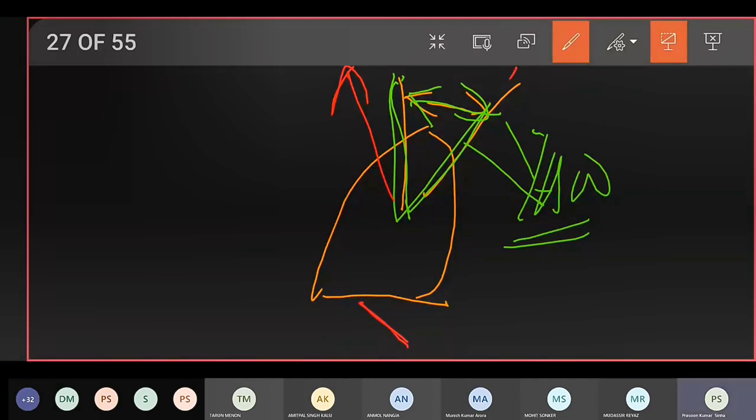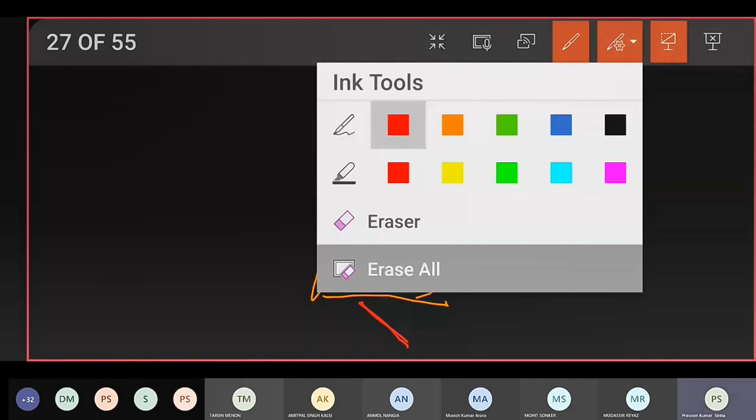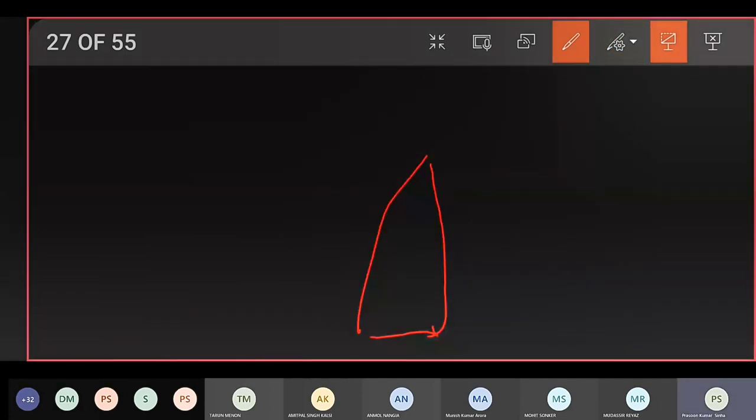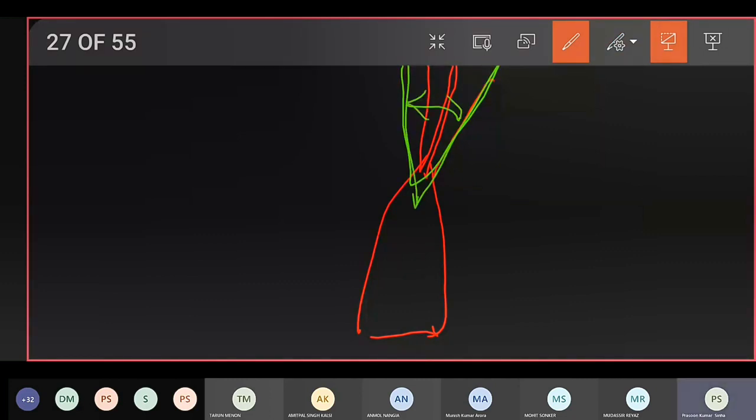So this is called yaw setting, that is, how much change of heading is allowed before the rudder is applied. Naturally, in good weather, with no waves, nothing, this limit will be very minimal. We don't want the ship to go beyond a small range of heading. But if the weather is bad, no matter what I do, the ship's heading keeps on going from here to here. So I open the yaw setting: turn as much as you like, dance as much as you like.